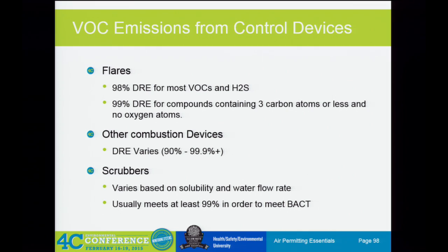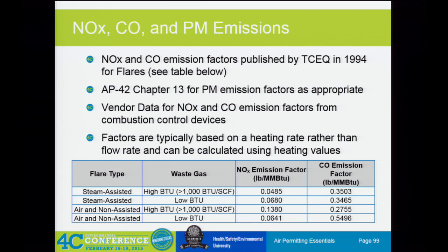Yes, you do. I believe that's coming. So for the NOx and CO, they're going to be off of factors. For the VOC, we use a DRE, which is applied to the flow rate that's going to the stream, and then a fraction of that will be emitted.